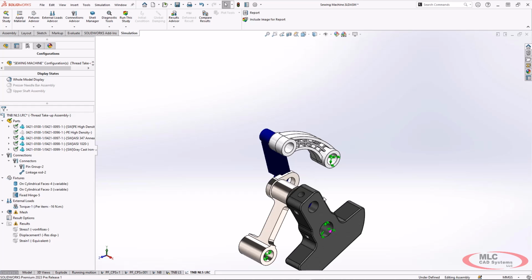So there are some great new features available in SOLIDWORKS Simulation 2023. We got this contact penalty stiffness option that we talked about that allows us to sacrifice local accuracy in areas of contact in order to get a much faster solve time, and then bring it back when we do our final analysis. We've got more flexibility in our bonded contacts, being able to handle more off-skew faces. We've got diagnostic tools that we can quickly access, including finding the underconstrained bodies option, which is great, and then also these virtual rod connectors in nonlinear studies.